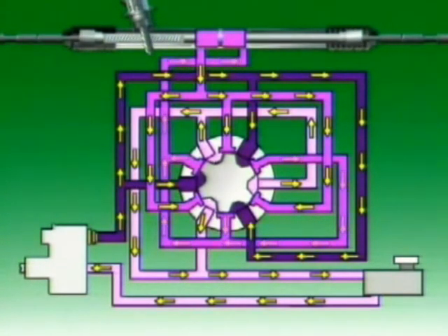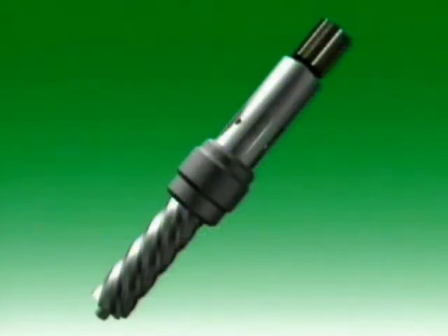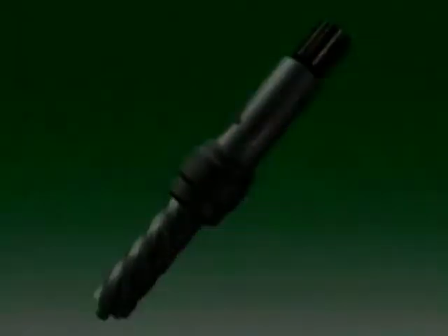Slight rotation of the valve gives a small amount of assistance, which becomes progressively greater as the torsion bar flexes, and more assistance is needed. The grooves of the inner member are precisely shaped to meter the flow of fluid.